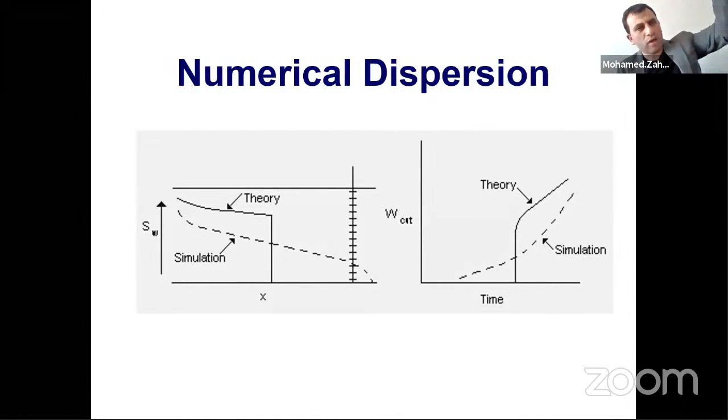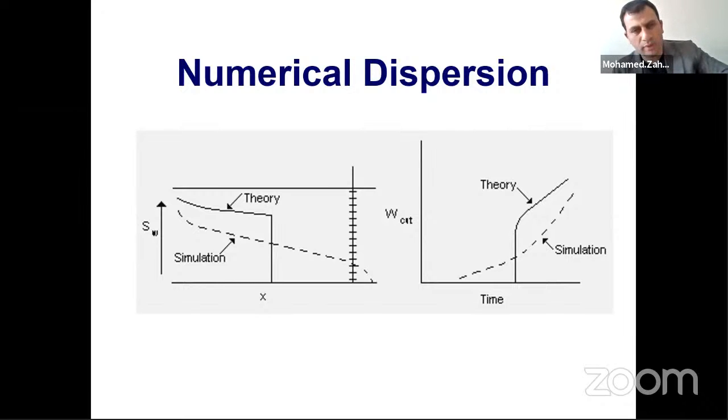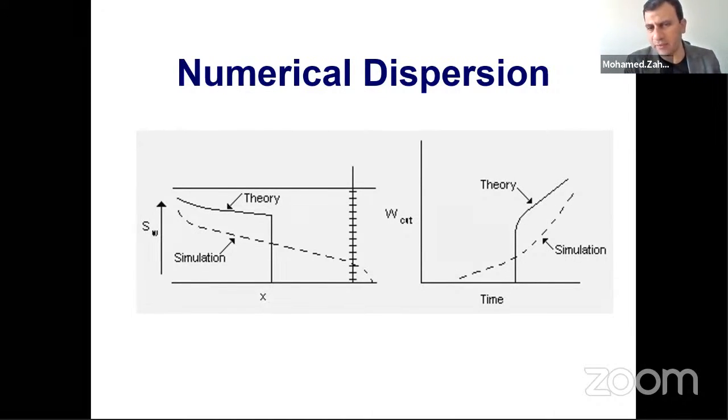If I have a thick reservoir, the pressure at the bottom is higher than the pressure at the top. That's why, if both cases are above the bubble point, the viscosity will be higher at the bottom than at the top. The formation volume factor at the bottom will be lower than at the shallow part of the reservoir. That's why the accuracy of the simulation in calculating oil in place is a little bit higher than the static volume.